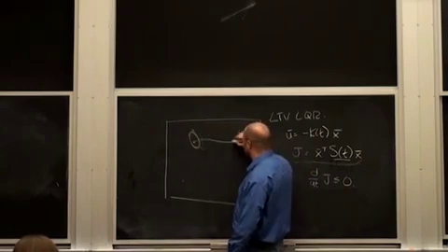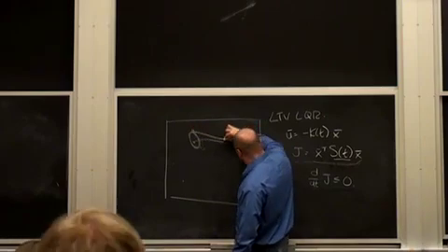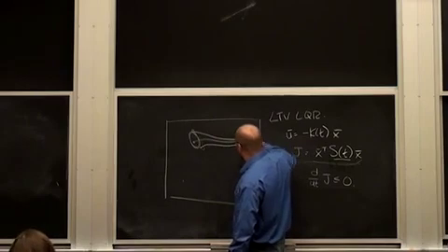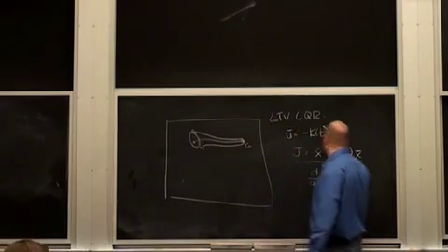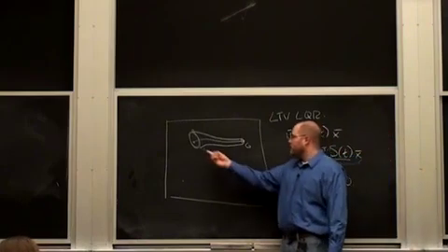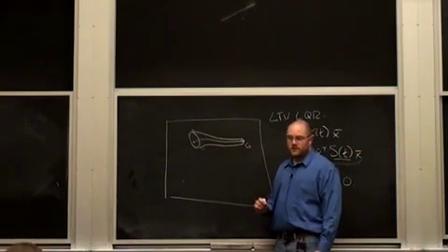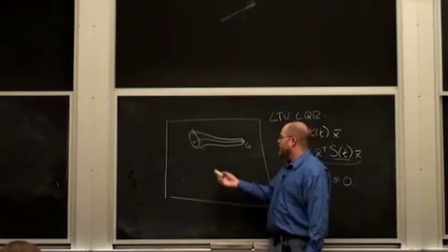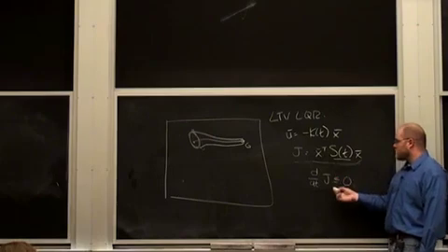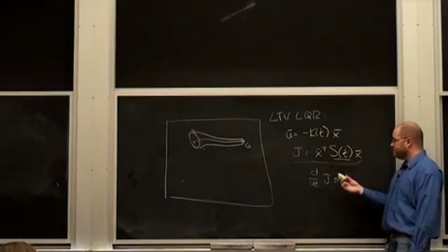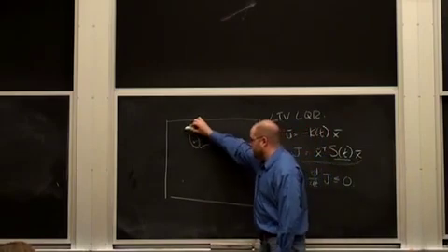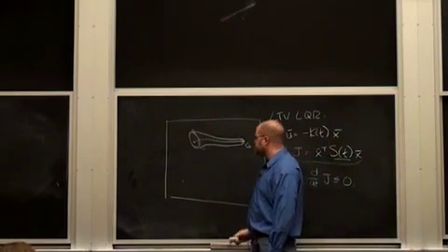If I do it everywhere in time, that gives me a funnel along the trajectory over which I know the LQR cost to go is a Lyapunov function for the nonlinear system. And the way that we construct that threshold is mostly conservative, meaning the real basin of attraction should be bigger than this estimate.